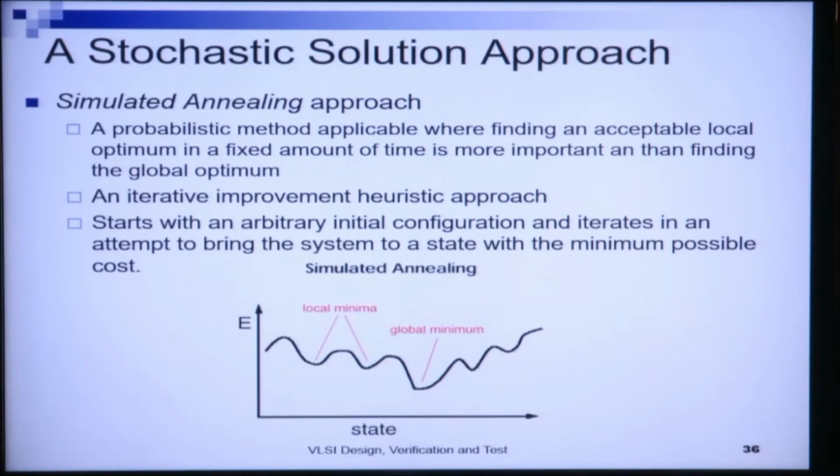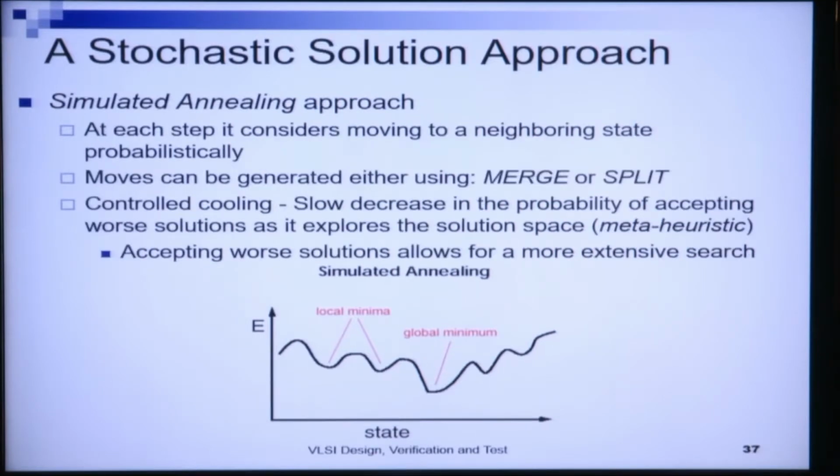So it is an iterative improvement heuristic approach, and it starts with an arbitrary initial configuration and iterates over the state space in an attempt to bring the system to a state with the minimum possible cost, let us say in terms of area. So we will now look deeper into the simulated annealing approach.